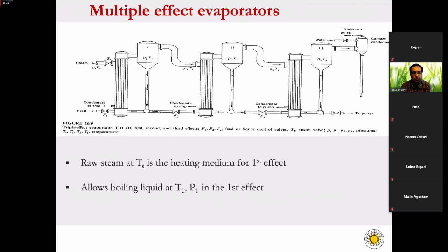Then I will proceed. And since we have been talking about how we can perform energy balance in single effect evaporators, now we have to think about how we can perform energy and material balances for multi effect evaporators, right? So normally it is quite similar, but the difference is that you only provide steam in the first evaporator, and then the vapors from each effect will become a heating medium for second effect, for the third effect, and